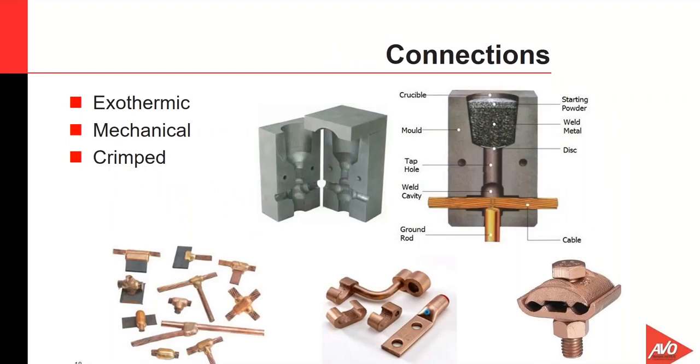It says a little more about how the connections should also be strong enough to withstand maximum expected fault currents and resist corrosion for the intended life of the installation. If you're interested, IEEE Standard 837-1989 gives detailed information on the application and testing of these types of connections inside a substation grounding system. Unfortunately, with time constraints, we could talk all day about grounding and substations, but we've got to keep moving on. We'll get into fences now a little bit.